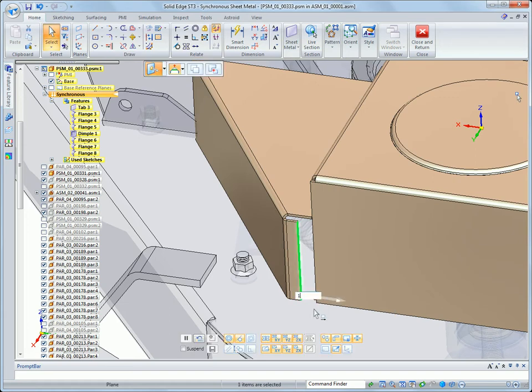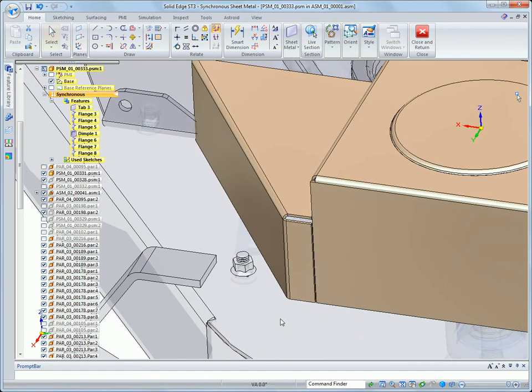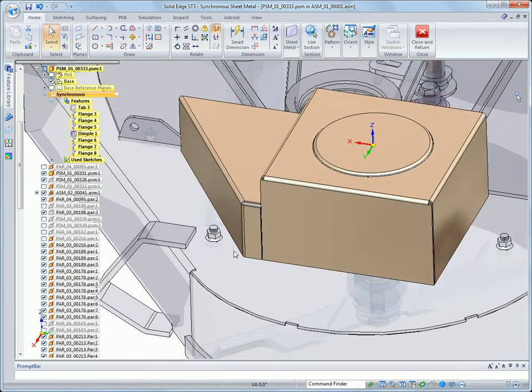By offsetting the steering wheel tool from the thickness face 1 mm, we can quickly establish a 1 mm gap between the 2 faces by selecting a key point during the drag and edit of the thickness face.